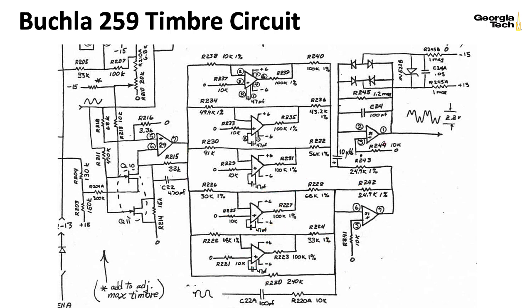But I have another inverting amplifier here. So what is this one taking? Well, it's taking the output of this op amp, that mixing stage, and it's mixing that with the output of this circuit, and this circuit. So those are all getting mixed here. So the original input and these two stages are being mixed in with a plus sign because it's been inverted twice. And these three stages are being mixed in with a minus sign since they're getting inverted once.